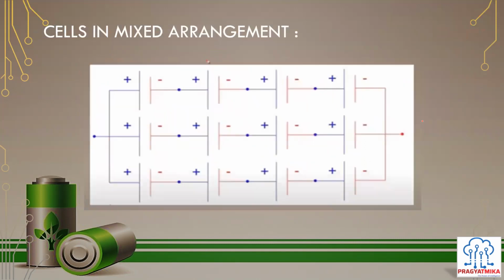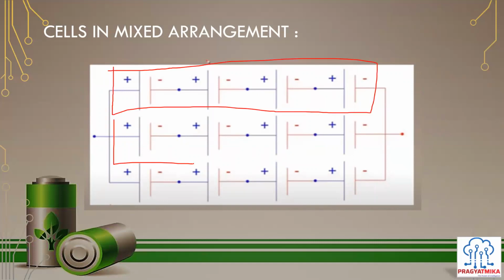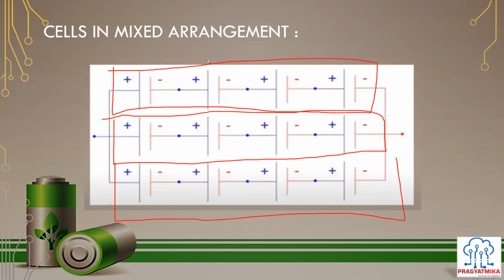There is another method where we connect the cells in series first. So this is a series-oriented connection we are doing. Here we do the series arrangement, and then these strings are connected in parallel. So out of this it is 14.8 volt, 10 Ah.